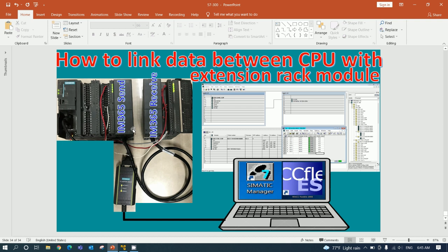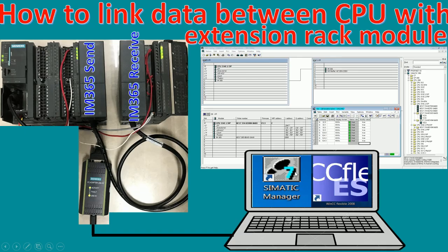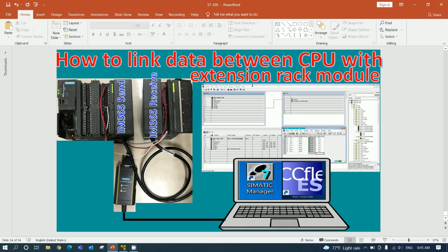And for the nameplate, we need to put the same as here. Yes, the nameplate, because if we put the wrong part number, when we download, it will fault the CPU, right? So here I will insert it.